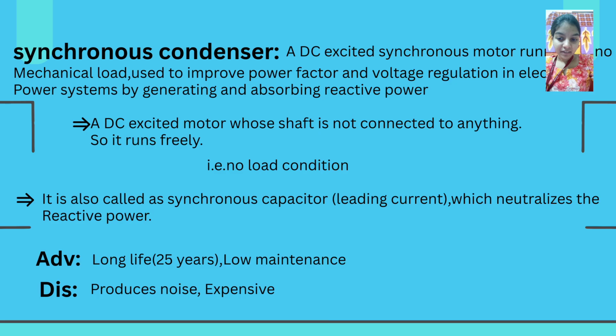Synchronous capacitor gives leading current, which neutralizes the reactive power. Reactive power means inductive component. So by providing leading current, we will neutralize the lagging current. So the advantages of the synchronous condenser are a long life, low maintenance. Disadvantages are it produces noise and is expensive.